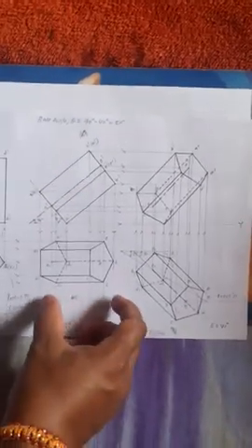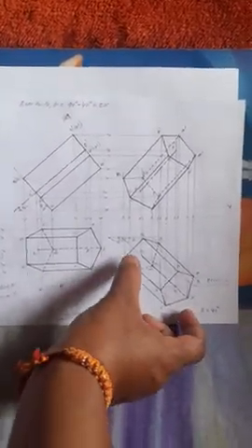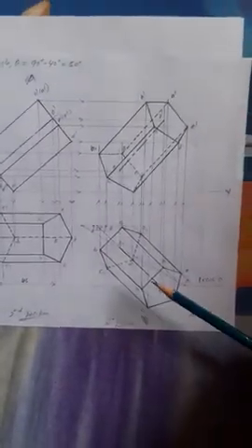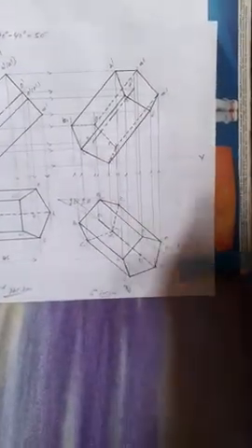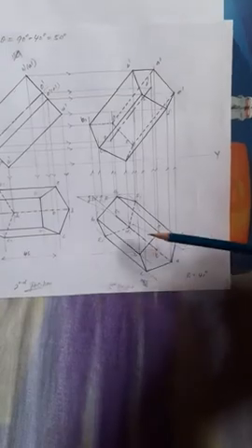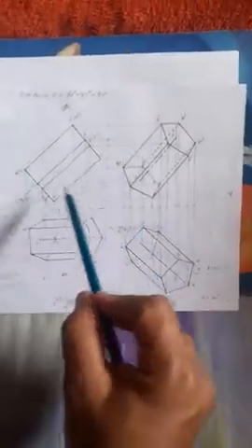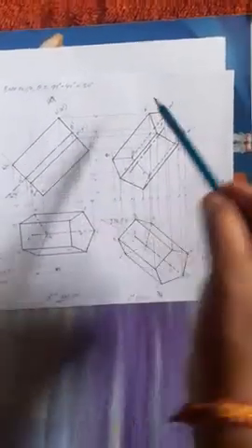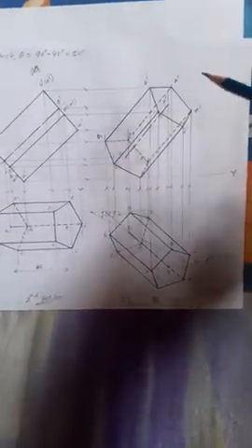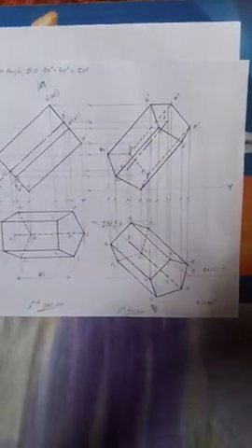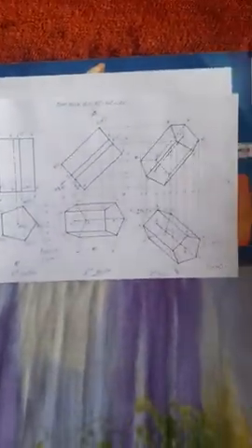Just transfer this second position top view on the beta degree line. Redraw that solid. Now we will get the third position, top view. Now vertically project from each corner of the third position top view, and horizontally project from the second position front view; the intersection points are there. Then apply the concept of visible and invisible corners, edges and lines, right? Try to solve this problem. Okay, thank you for watching this video.